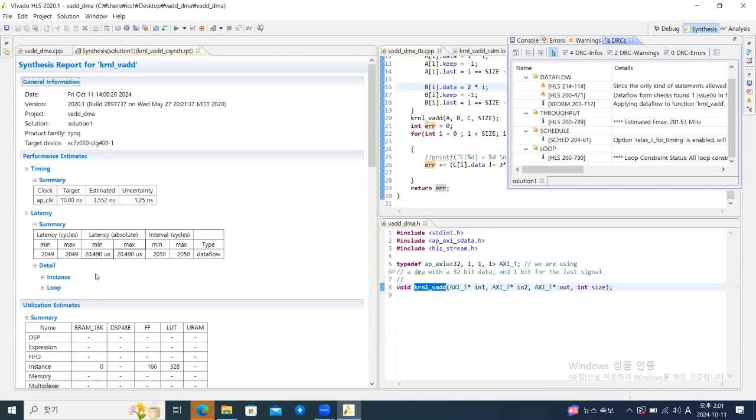So what we would like to do is make a streaming architecture where the data flows from the input DMA and just automatically adds and goes to the upstream. For these kinds of streaming architectures, from the hardware architecture view, it is basically a FIFO. You have a bunch of FIFOs for the input and output data, and right next to the FIFO, you have the addition and the load and store units. So let's see the analysis view right now.